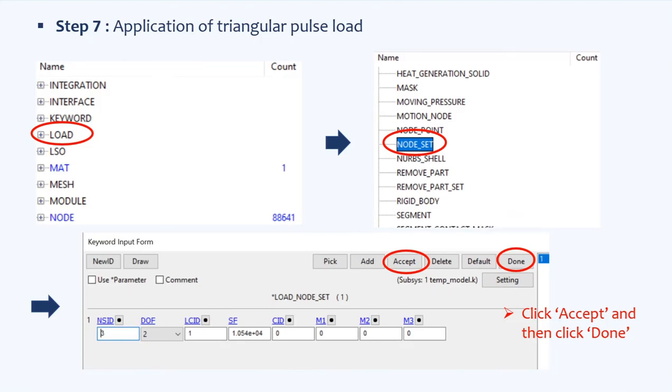So your column will be subjected to a total load of 4,500 kilonewton. That 4,500 kilonewton will be applied as nodal loads throughout the face of your column. So you apply it as nodal loads to 427 nodes. At the face of your column, when you select the number of nodes, you can see a total of 427 will come.